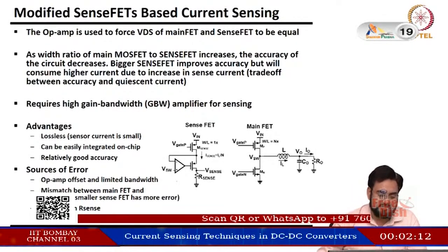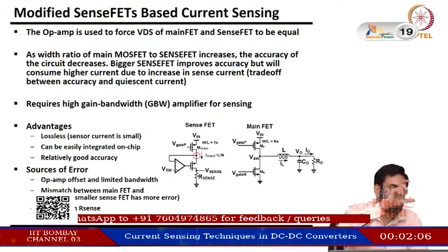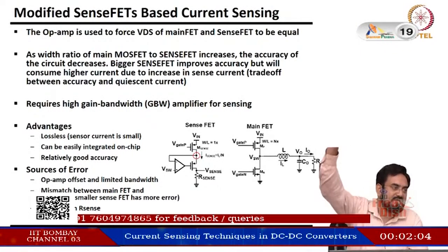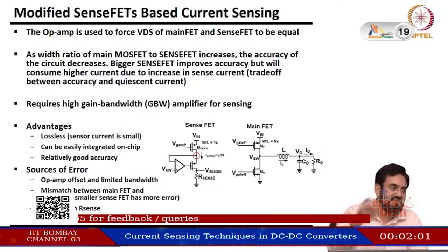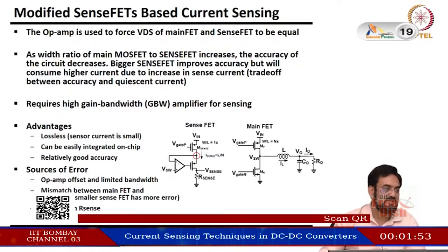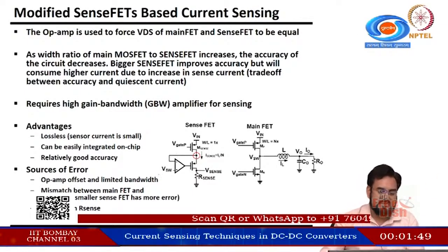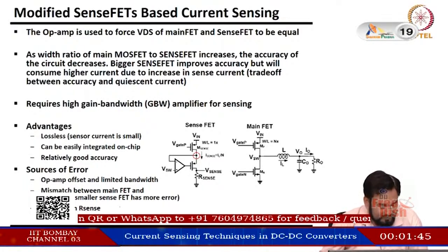Okay, so I am looking here, this is a ramp actually. If you look at the voltage difference, it is a ramp because the current is rising, so the voltage will be a ramp here. So this has to track that ramp, and if I am not able to track properly, which means the bandwidth is smaller, then I will always have some delta error, and that error will cause a difference in the current. So accuracy will go bad.